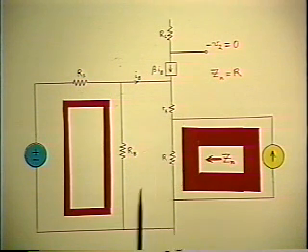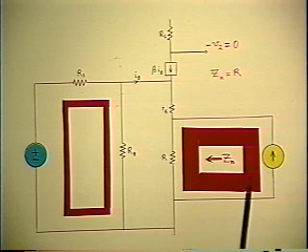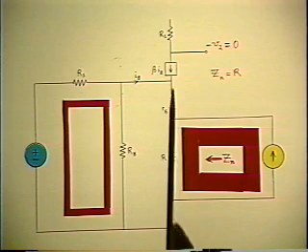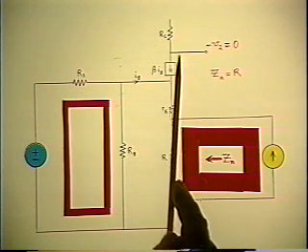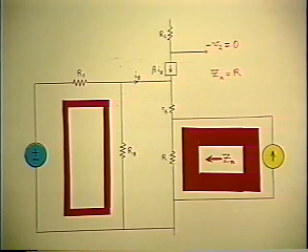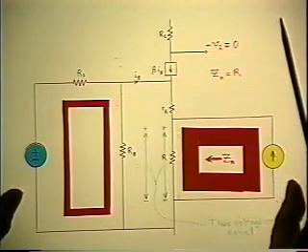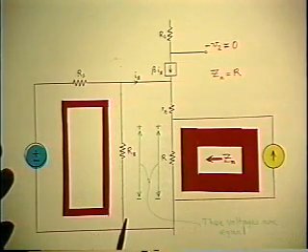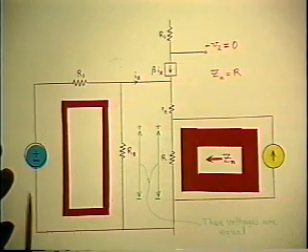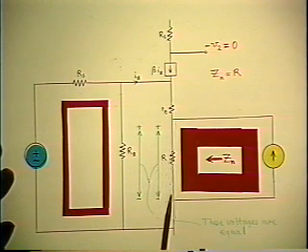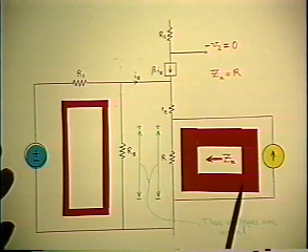And this makes it even more clear now why the answer for Zn is just R, because the null that you get at the output implies zero drive to the transistor as well, which you have set up by adjusting the two sources so that the drop across RB caused by this loop current is matched exactly by the drop across R caused by the other loop current.